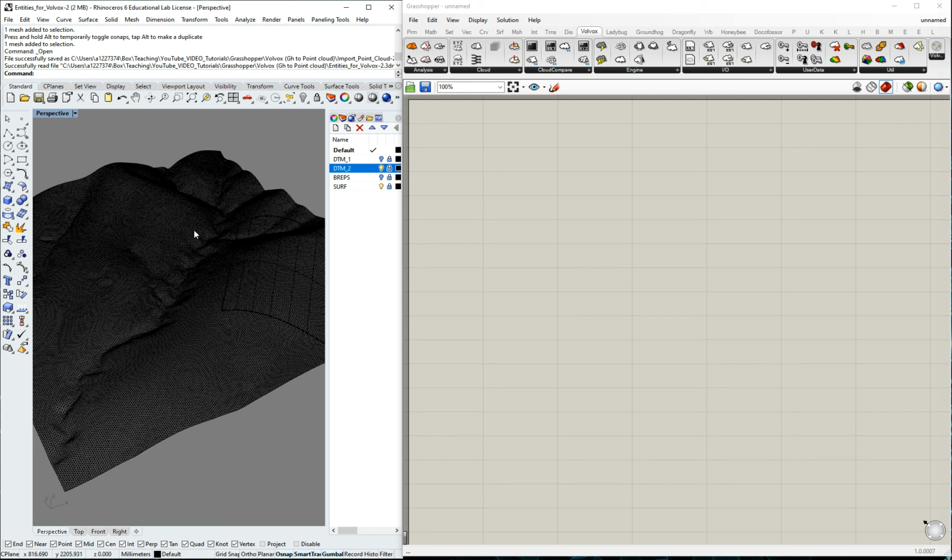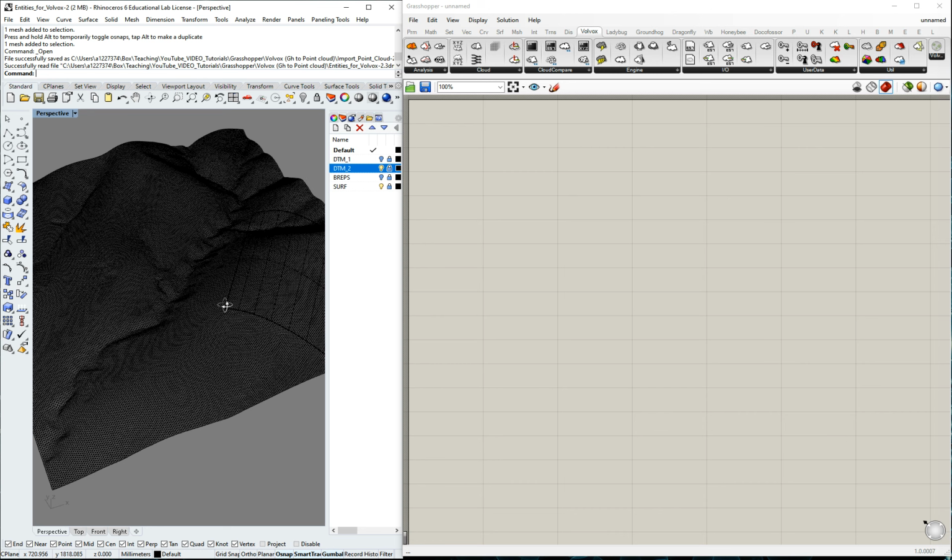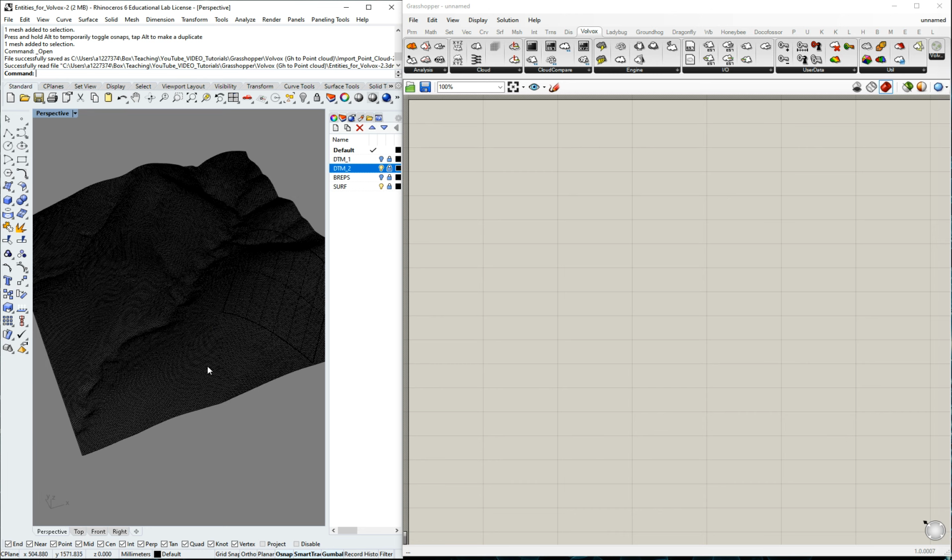Now, let's imagine you derive this from a LiDAR point cloud. The LiDAR has a geolocated position. As soon as you insert it into Grasshopper and Rhino, this geolocation or georeference is lost, and the new reference will be the X, Y, and Z of Grasshopper and Rhino, the new origin. So bear in mind that if you want to extract something from this and merge it with an existing point cloud which has a geolocation, the entities may not overlap with each other.